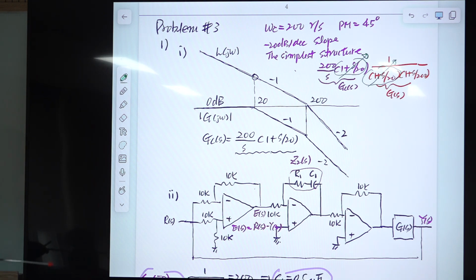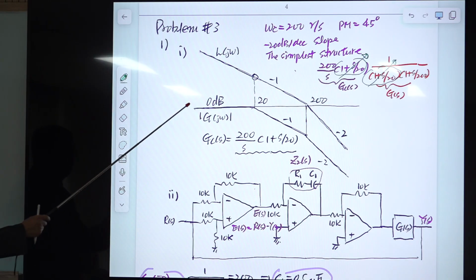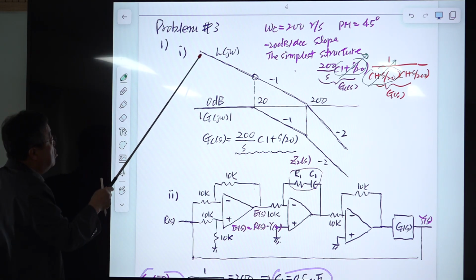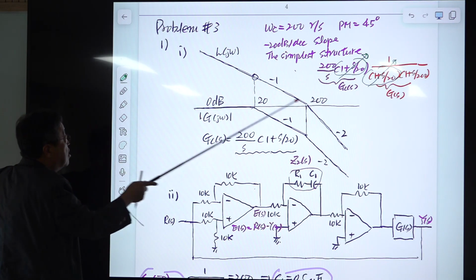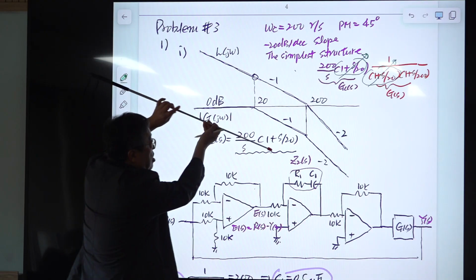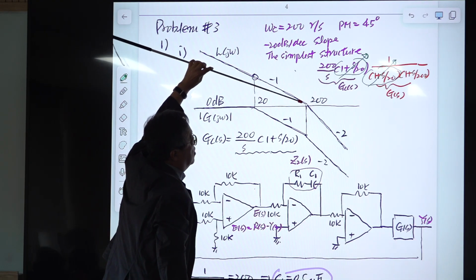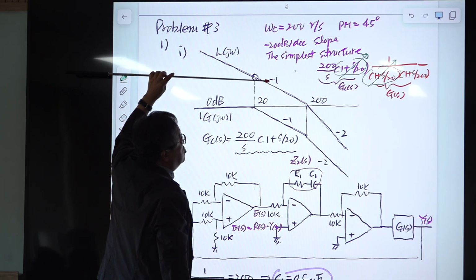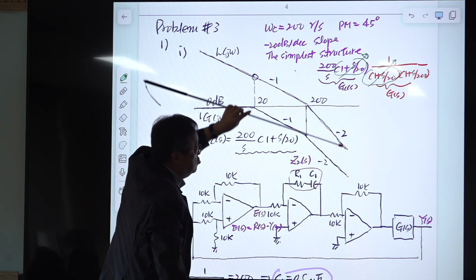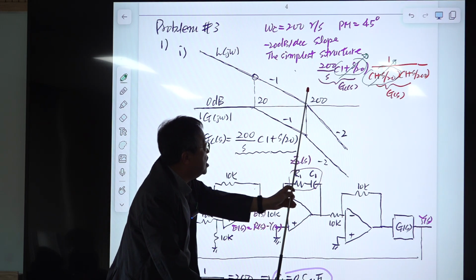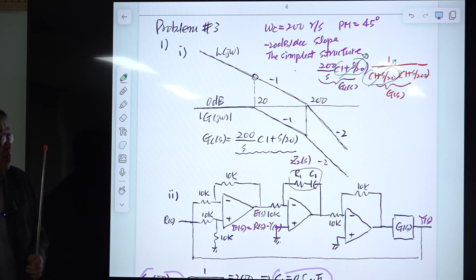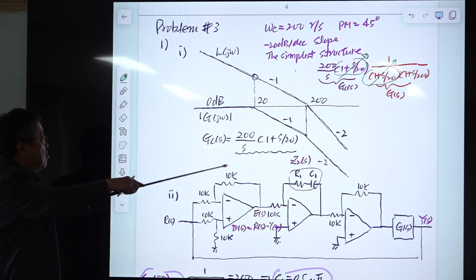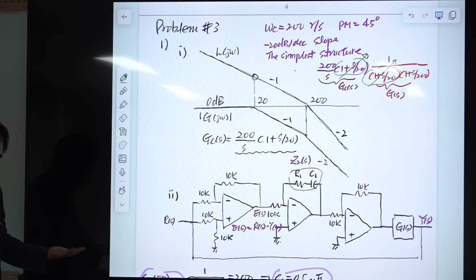So you need one 0, and the integrator to have integrated structure, and the integrator is selected at this value, then the integrator is going like this, and it has a pole, so the slope will be changed from -1 to -2. Then this is the corner frequency. Phase at this point will be 45 degrees. Okay. Then with this, the design goal is achieved.